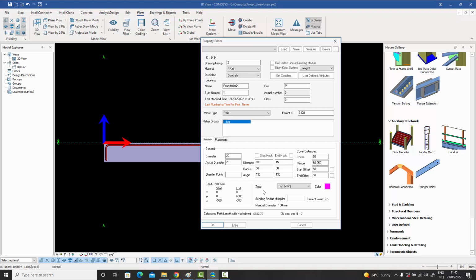The other type is over here, which is basically the type of the rebar itself. And usually the most common types are the top main reinforcement, the top secondary reinforcement, the bottom main, the bottom secondary, longitudinal stirrups, cross ties. Those are the most commonly used rebar types. So if I were to open this, you have all these different options of stirrups, top main, top secondary, bottom main, bottom secondary, longitudinal, chairs, anchor bolts, depending on, I mean, we've got lots of options, cross ties, mesh reinforcement.